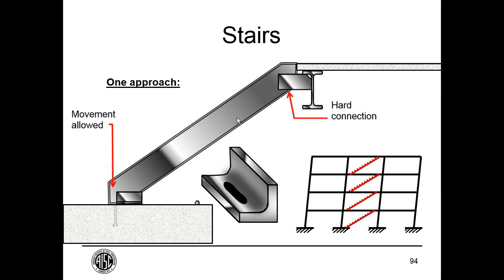All right. So the necessity of having a slotted connection here really depends on the lateral system and also on the stair system that you have. If you have a wood-framed house, you've got probably a fairly compatible system all the way through. Your shear walls have some flexibility, but your construction of your stair, it's continuously supported, nailed into a wood wall, and it's really not something to worry about.